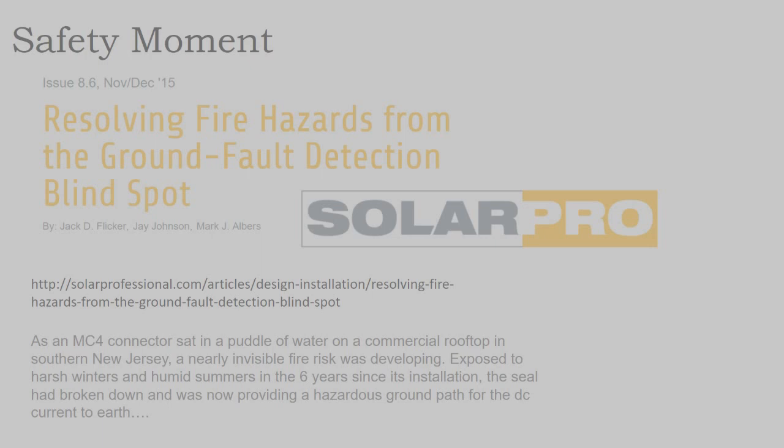In fact, in your old school central inverters, the way that their ground fault detection circuit was intentionally grounded, it's called a grounded inverter, and it really has to do with how the DC side ground fault detection detects ground faults.